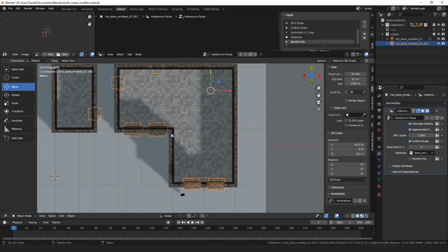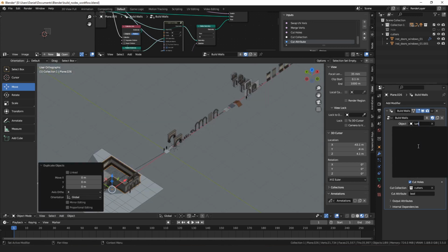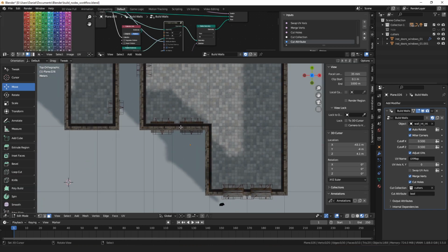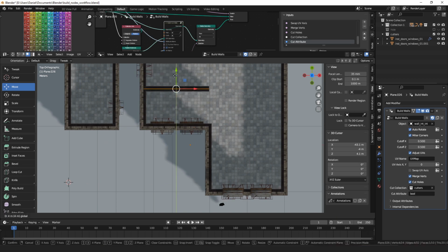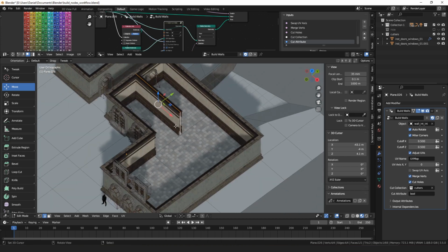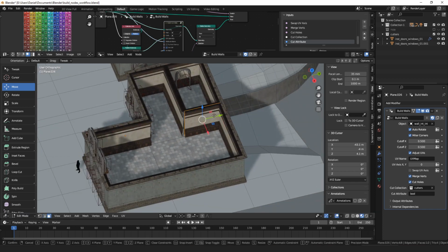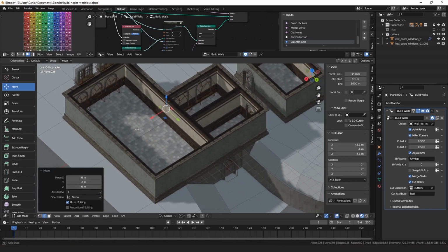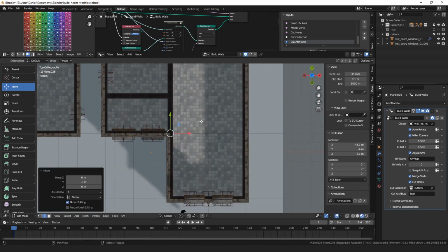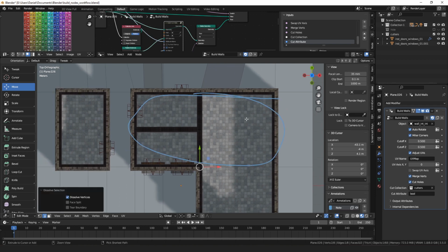Then we could try to come up with a bit of a plan. We could make a copy of our walls here and select the interior walls. We'll just separate this and invert the selection, delete everything. Now it's just a matter of deciding how we want to divide up this room. So somewhere here, the basement's only under this part. So we're going to need a staircase going down probably into that.